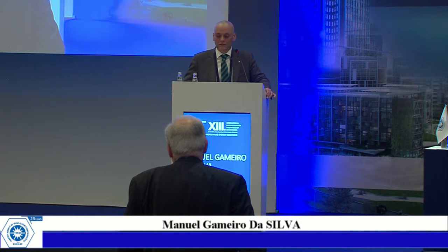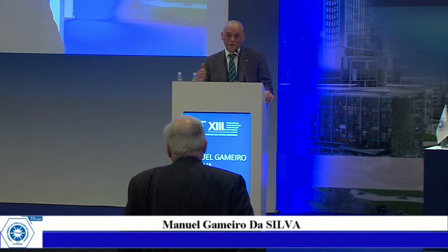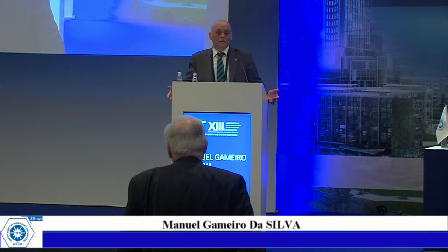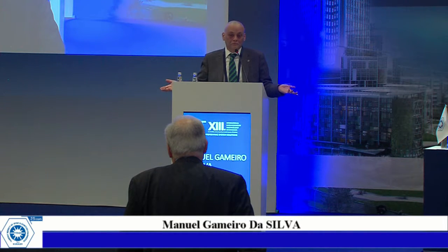Humidity becomes important when you need sweating. And so if you are in a comfortable environment with a sedentary activity level, humidity is not so important. So this is one reason. And the other restriction in the adaptive model regarding PMV is that you are considering that the metabolic rate is 1.2. Besides that, it's the same thing.